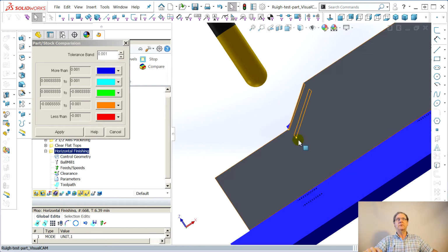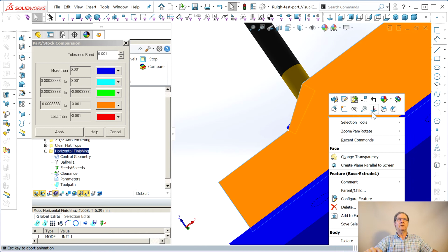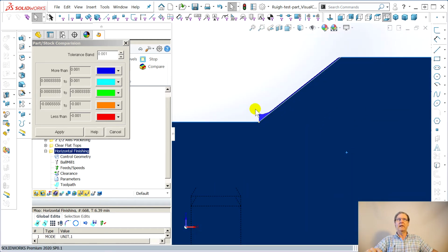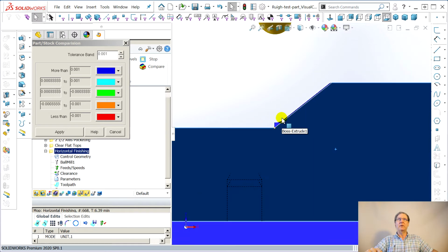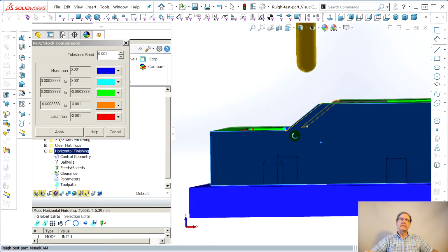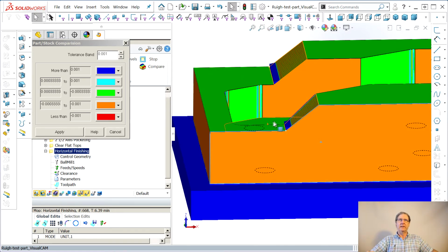Can you move the tool? Probably not. Here's how we do that. Okay, and then zoom up. See, it could go lower, right? It's really not bringing that ball mill down, I don't think. I did figure out how to do that on SolidWorks. This is the furthest I've got. I didn't expect I'd get this far without it crashing. So there's that same problem, that's why I initially did select this area. That's how I fixed SolidWorks CAM. I told it, do this area, and down it came.